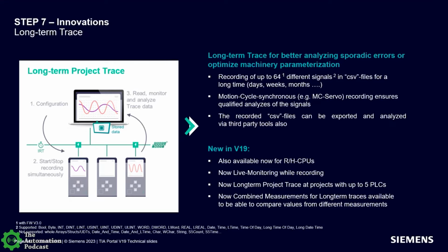Trace has been part of the 1500 since the inception, basically, of version 1. Fundamentally, that was a trace that's real and running against the real main program or the cyclic OB and capturing the measurements or the values of the tags related to the PLC. Over the years, we've extended it to support the ability of combining measurements or signals from one PLC to another PLC to a drive, because the drive also has the same